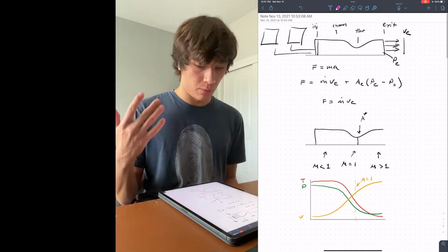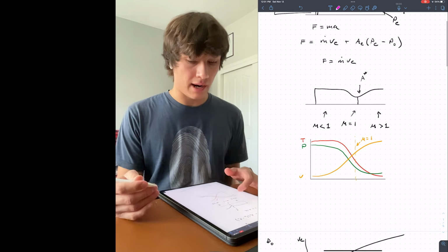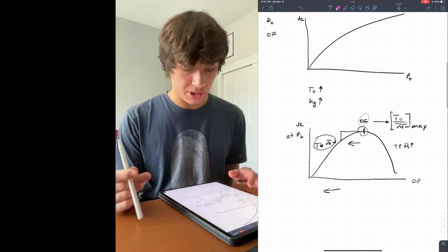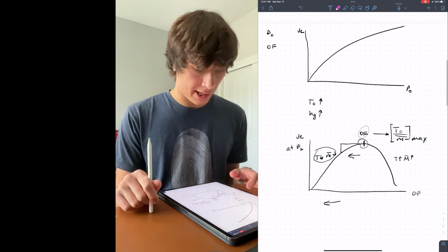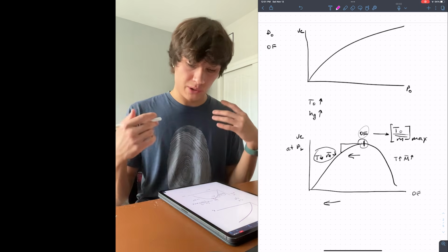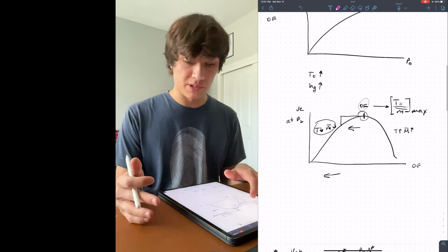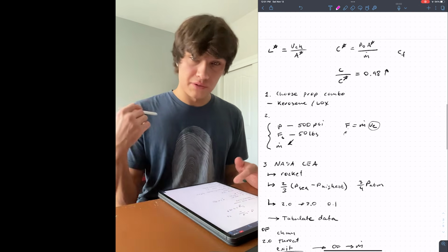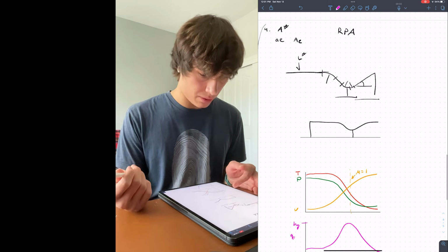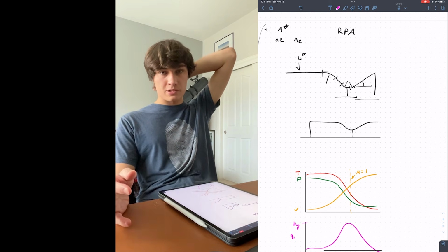All right, cool. So we went over high-level rocket engine concepts. We talked about how gas properties vary, what the assumptions are. We talked about the Mach number equation, which is really important. We talked about the isentropic gas relations. We talked about what governs the exhaust velocity in a rocket engine. We talked about how chamber pressure and oxidizer fuel ratio affect rocket engine performance and other characteristics. I included a step-by-step guide on how to size the first rocket engine, and we talked a little bit about some heat transfer stuff. Hopefully this is a good introduction to sizing your first rocket engine.